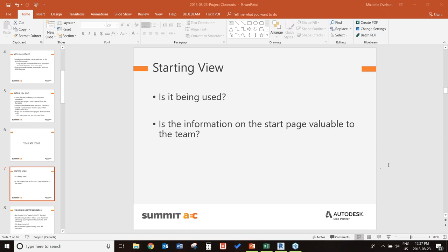Is there a shortcut to finding model in place families? You can probably find them with a Dynamo script. I'm not sure there's ever been something that really jumps out as in place other than the numbering. How I usually find them is if you go to a schedule of all your content, you're going to see something that says desk 1, desk 2, desk 3, desk 4, desk 5. If you see sequential numbers all with the same family name, there is a 97% chance that that's